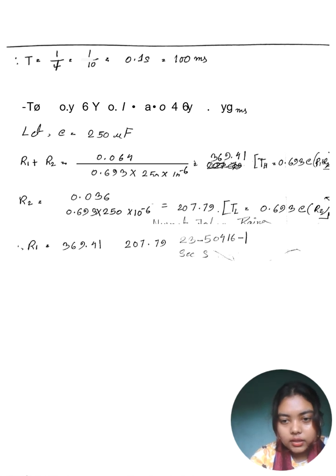Here we can see that it uses the calculated frequency from the previous page to find the total period time. It then calculates the high time TH and low time TL of the astable output pulse based on the duty cycle. TH is equal to duty cycle into T, which we can get as 64 ms, and TL is 1 minus duty cycle, which we get as 36 ms.